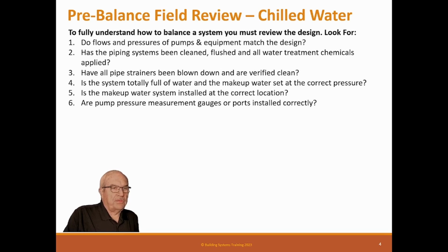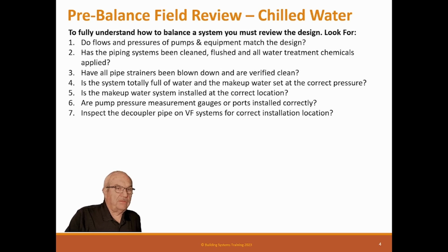Are pump pressure measurement gauges or ports installed correctly? This is the one that we find wrong about 50% of the time on jobs. No matter what the design says, a lot of times these will be installed in the wrong location. For us to read a pump curve, we need to know the inlet pressure at the exact inlet of the pump and the outlet pressure at the exact outlet of the pump. It can't be 20 feet down the pipe or on the other side of the check valve or on the other side of the strainer. That won't allow us to read the pump, so you have to make sure those are in the right location.